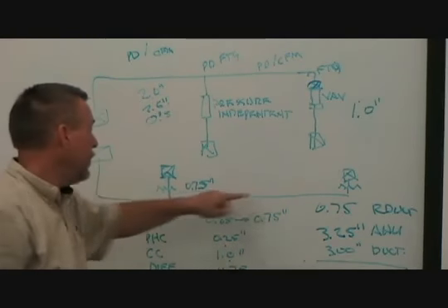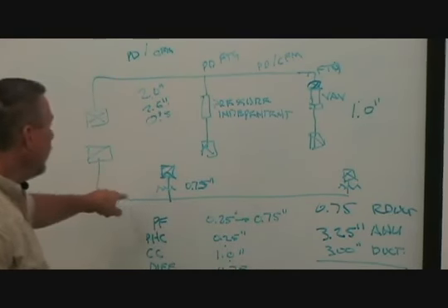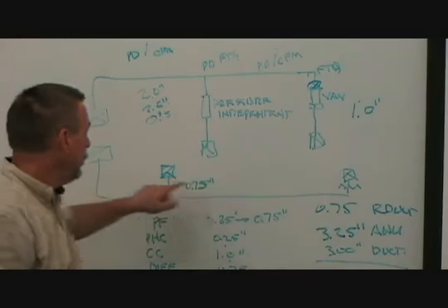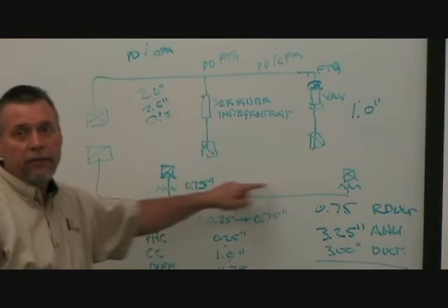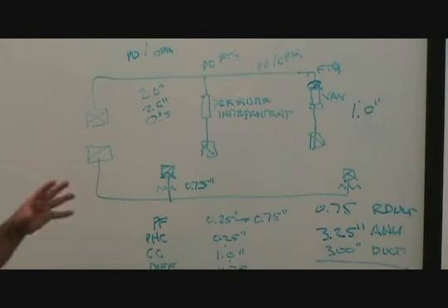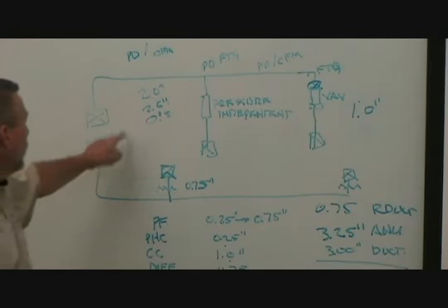This is not pressure independent. It varies, but it varies proportionally. So theoretically, once I balance these grills, I get the same proportion as the airflow goes up and down the supply.